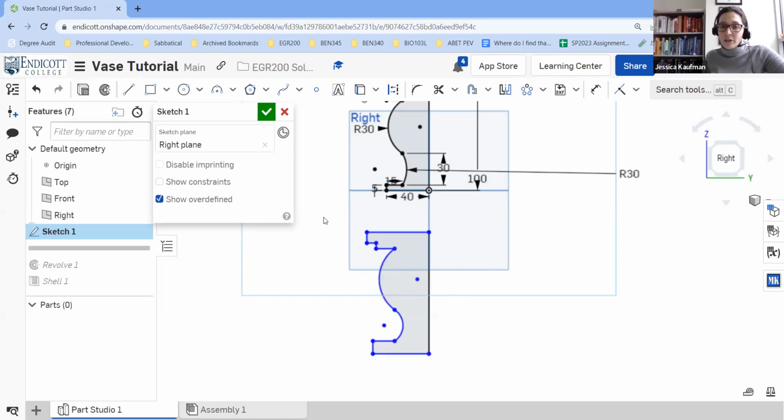One of the things that I want to do before I do any other dimensions is I want to use the dimension tool to define the distance to the origin. The other shape is actually at the origin, so this is an extra dimension that I'll need. And I'm going to make it be 50 millimeters, actually closer to 40 millimeters, just so that that isn't something that stops it from being constrained when I'm finished.